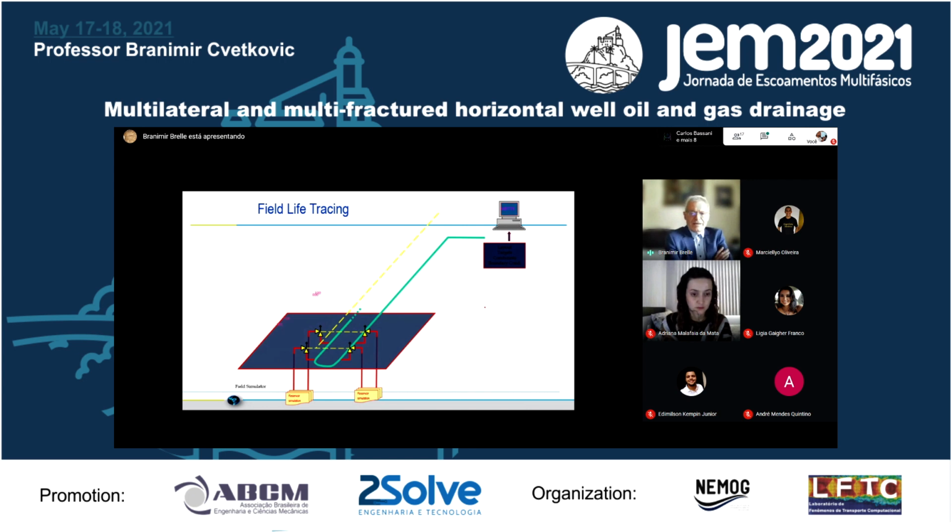So in each delta T, you are connecting the reservoir model. In each delta T, you are transferring pressure, the reservoir pressure and saturation, to the network pressure and saturation. And that is how you are getting the final flow, with the whole conceptual model.